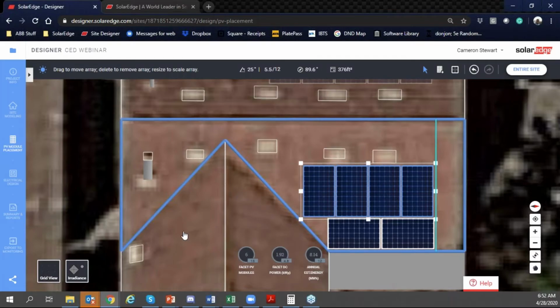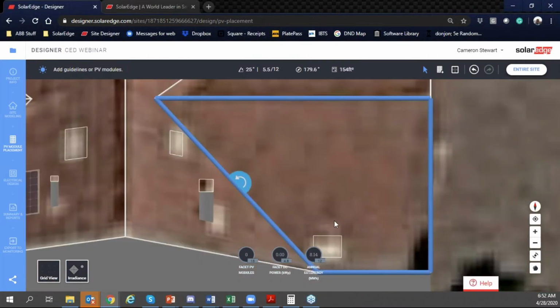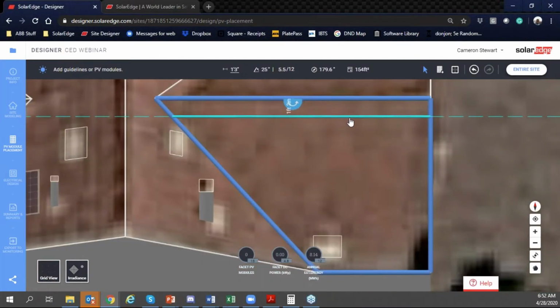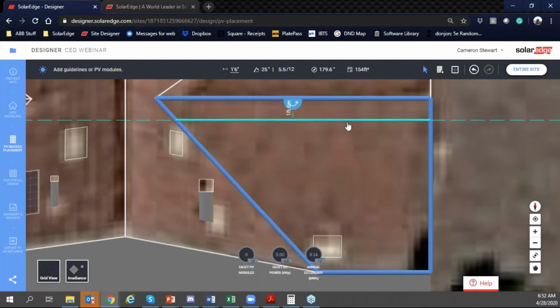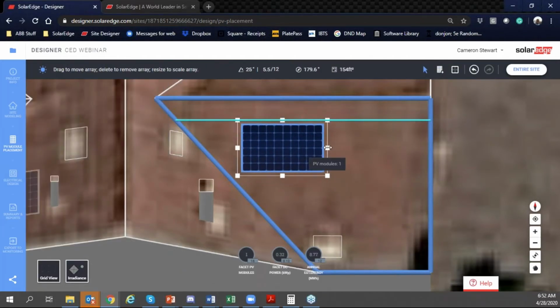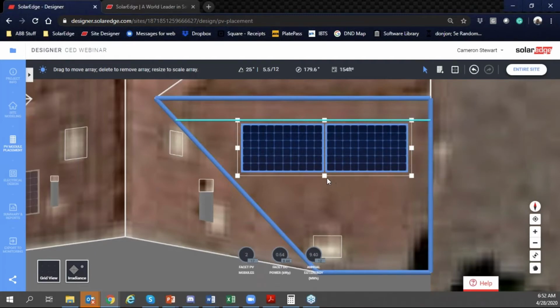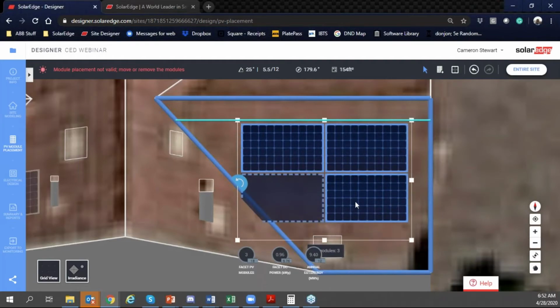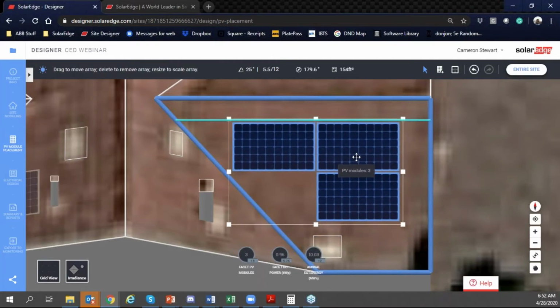Great. And then I might be able to get 1 or 2 more panels on this roof surface. Let's see. If we had a 1.5 foot walking lane here, and again, the justification, like I want to face panels on the north side. The justification, I think in the new California code, says that if you define an access point, which would be the other side of this roof, then you don't have to worry about the 3 foot walking lane on this side. Okay. Some of you are like, what are walking lanes? Man, this poor array is just all segmented and sad and lonely.